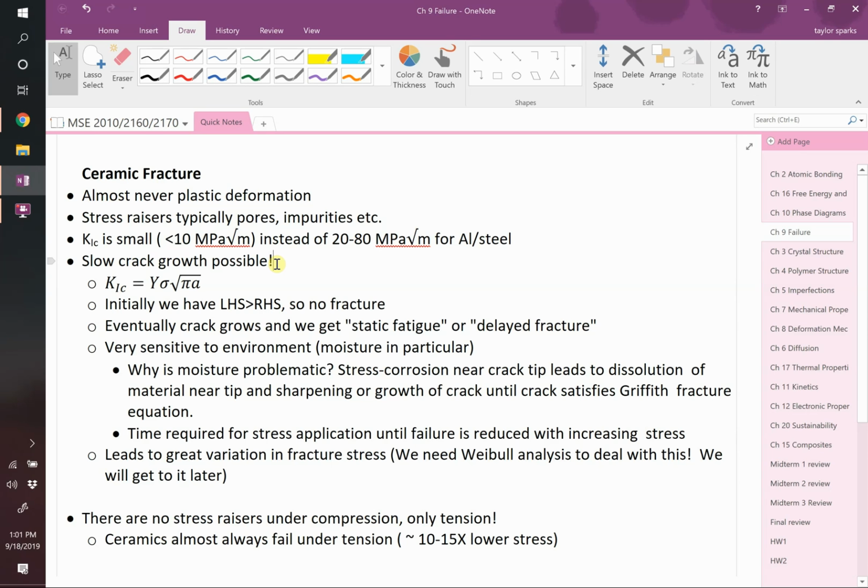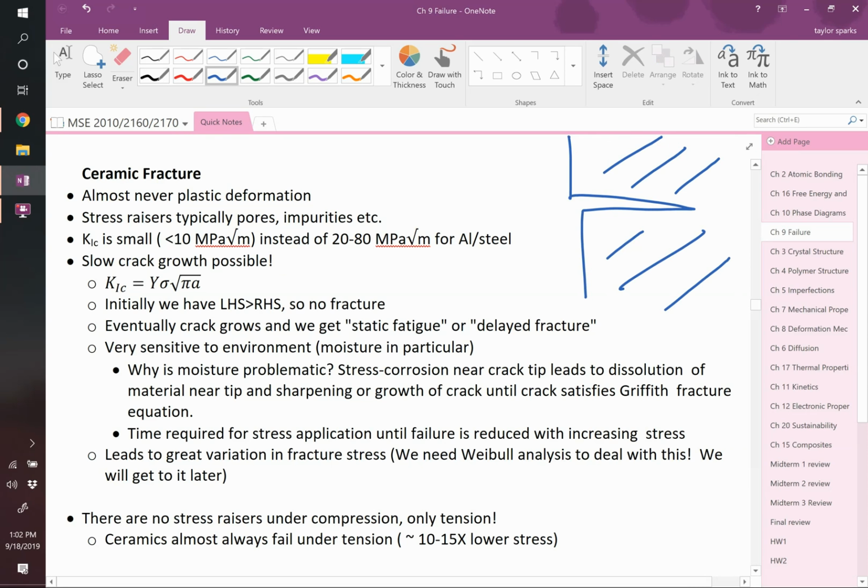When a crack grows differently because of the environment around it, that's the corrosion part of it. So it's not an electrochemical corrosion. This is a physical change. And what happens is that when you've got a tip of your crack, right, so you've got your material, has some cracked tip, right, so this is your material. At the tip of that crack where you have a very high radius of curvature, the chemical potential is different at the tip of that crack than elsewhere in the material.